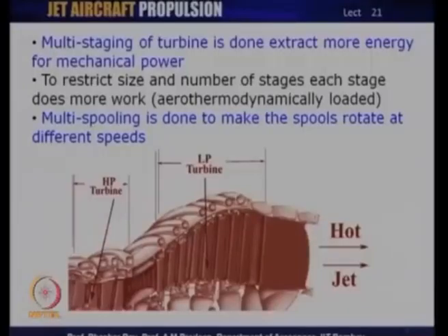In such a case, it is required that each of these stages is also highly loaded. Now, when we talk about loading, we are talking about aerothermodynamic loading. Some of these loading parameters are what we have talked about before with reference to your cycle analysis.